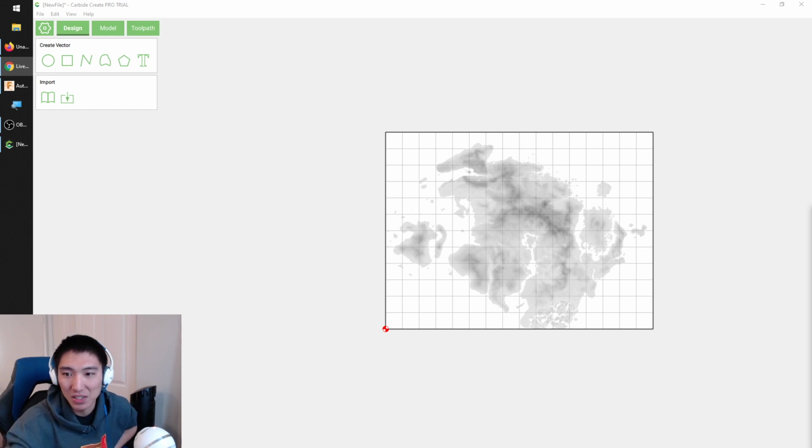You can also use a PCB drill, like a solid carbide tooling that tapers down to whatever diameter hole you want. Those are pretty useful instead of using a regular drill bit, where the shank is the same diameter as the cutting flutes.